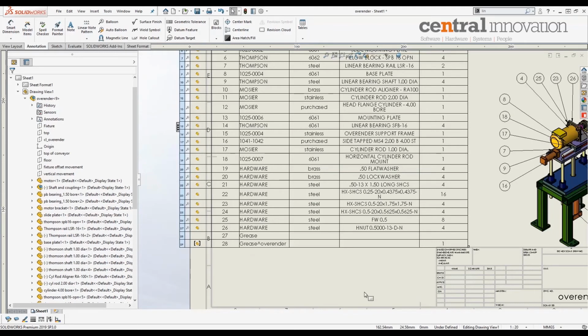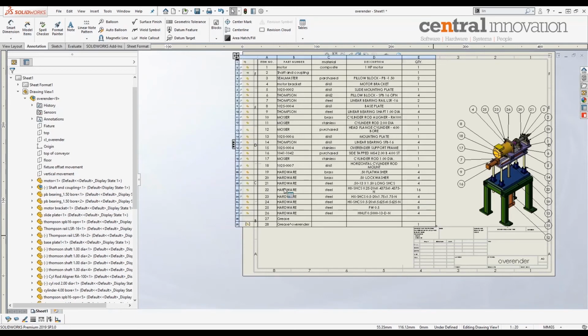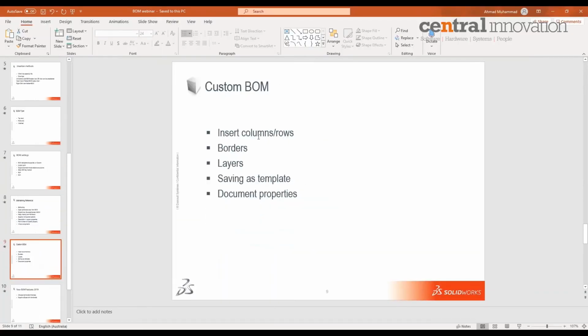And the reason I wanted to show the virtual components is people have other virtual components in their assemblies as well. In the bill of materials, the way to show virtual components is, again, with this little expansion tab, and the square brackets refer to this being a virtual component. And for that part, I can always go to the custom properties and specify a quantity or whatever information I want to populate for that particular virtual component.